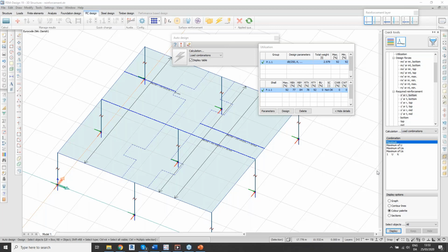It wasn't considered, as Flavio said, for shear verification. It was just applied a theoretical load. Basically, when you face that in a real project, you just increase the thickness because you don't place stirrups in very small thickness plates.